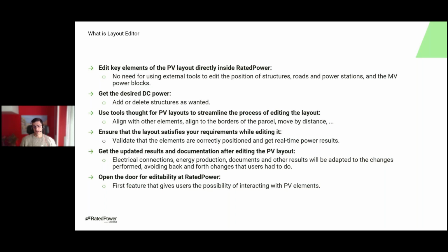Finally, it's also worth mentioning that once we have edited the PV layout, we will be able to get all the documentation updated. Results, electrical connections, energy production, topography, and so on will be adapted to the changes that we make. So we don't need to go back and forth with these changes, and all the documentation will be automatically updated with the changes that we made to the layout.